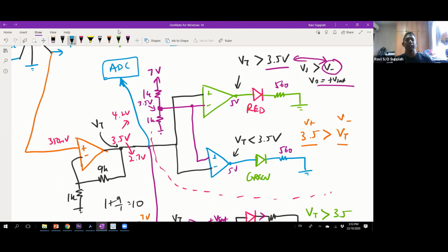Okay, so this example is exactly like how your IR sensor is going to be. The only thing is, after we get the signal, in our case, since our signal is already in a good range, correct, 2 to 4, 2 to 5 volts, we do not even need to do any amplification. We can straight away take the IR voltage and use the A to D operation, and then from the signal we can make the decision of how close you are to the wall. So this is basically what you're going to be doing.